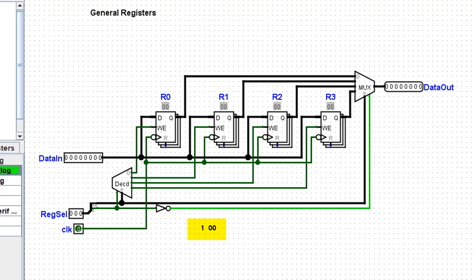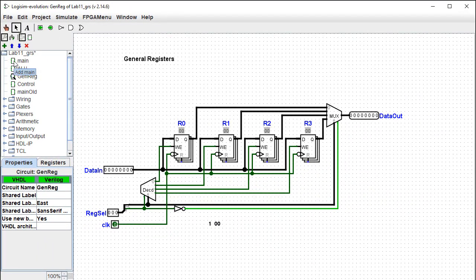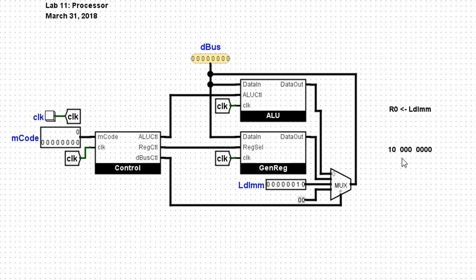With that 1 set, that signal is changed into a low, feeding that output mux, which deactivates the output mux. So nothing going on inside this register circuit is going to be fed to the outputs. And that's what we want in this case. So I know that next group of 3 needs to be 1, 0, 0.